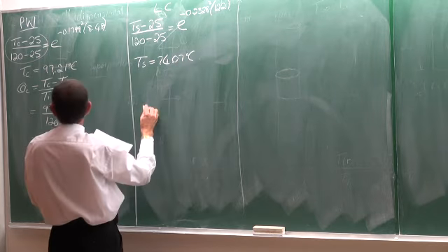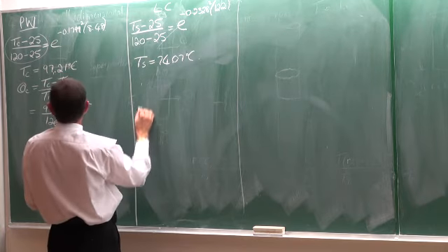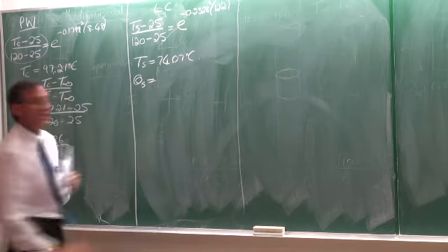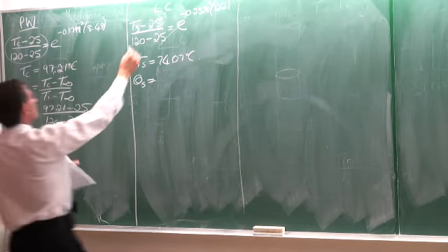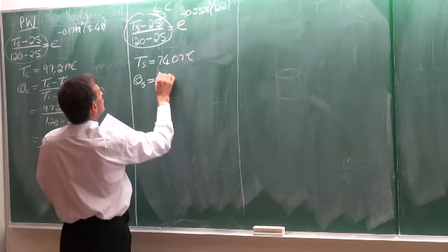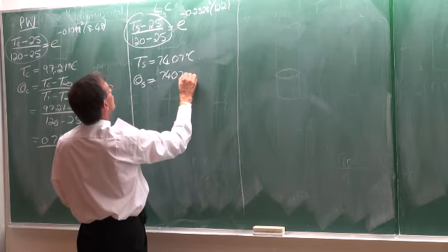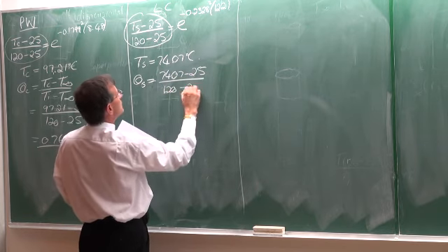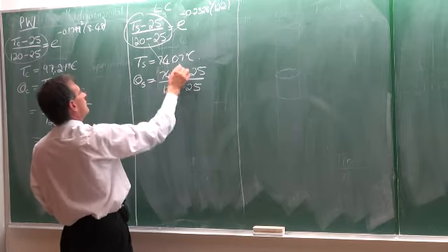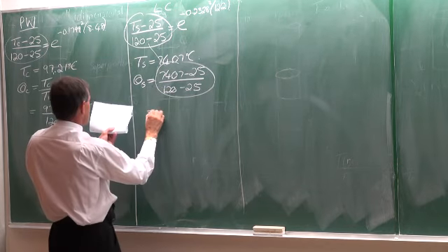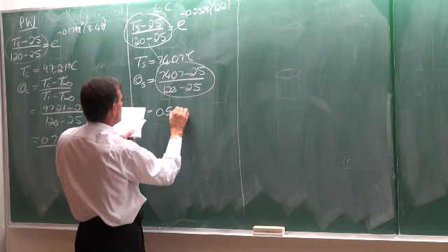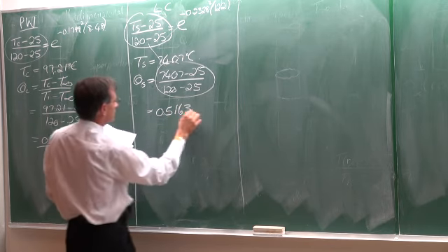74.07 degrees Celsius. And we can also solve the non-dimensionalized temperature at S, which is now 74.07 minus 25 divided by 120 minus 25. So it's those values there, and it gives us a non-dimensionalized temperature of 0.5163.